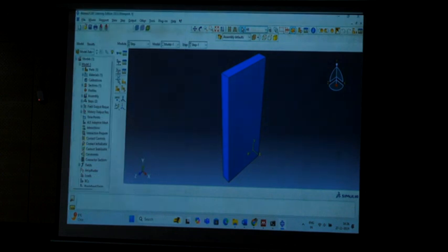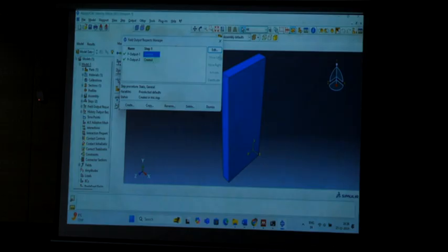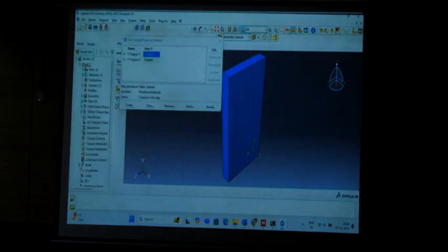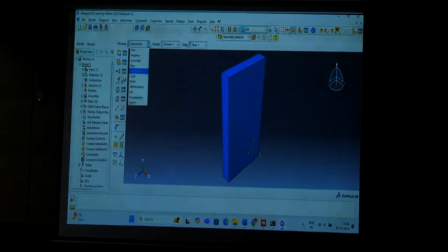Just click on OK. If you want to edit it again, you can go to the output option. Then we go for the interaction, but here we don't have any interaction, so go to the next option called load.